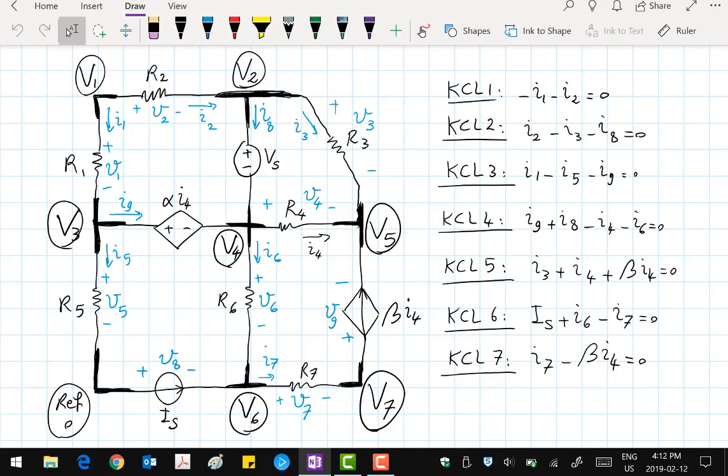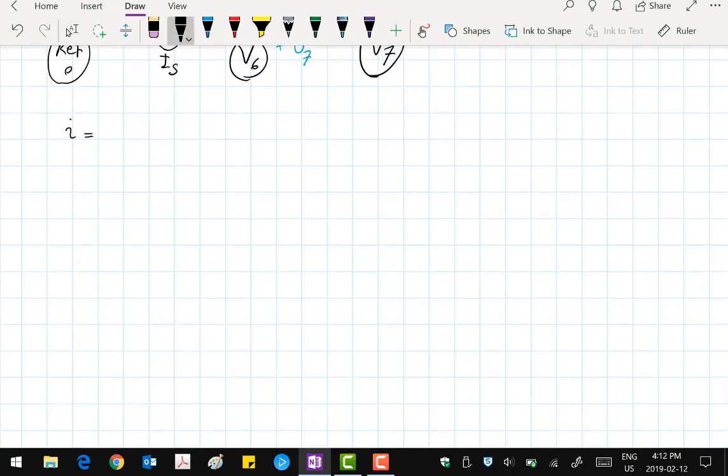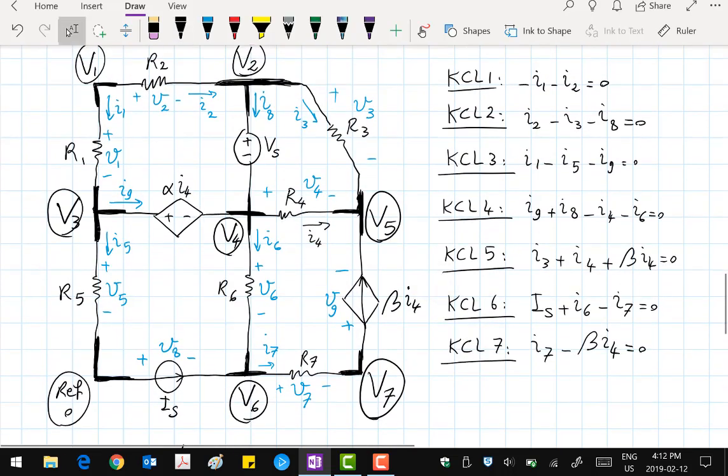And so next we are going to write these currents in terms of node voltages. And so for instance, for I1, let's take a look. I1 by Ohm's law is simply little v1 divided by R1. And little v1 is the difference between big V1 and big V3, those node voltages, right? So just as an example, I1 is V1 over R1, which is then this. And you can do this for all the other currents through the resistors, right?